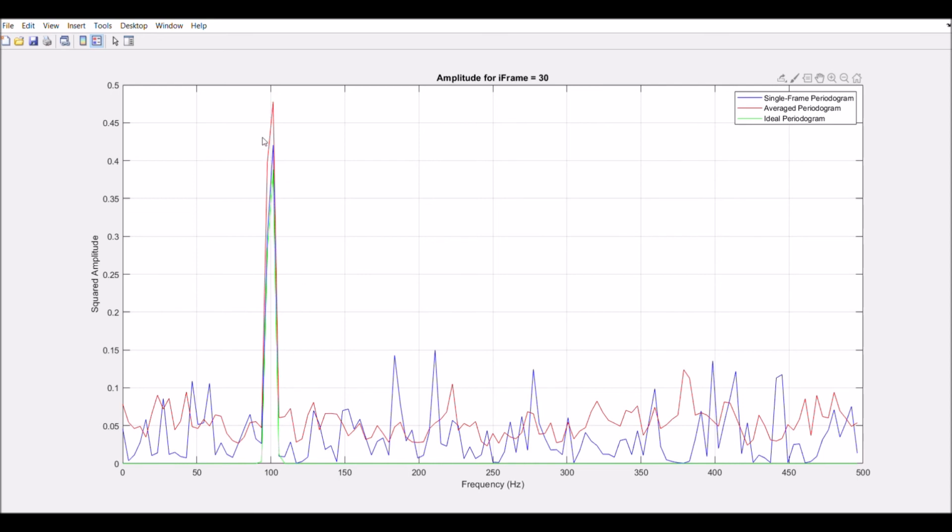And so we see that the peak is approximately where the other two peaks are, but two things have changed about the noise content. One, the bias, or the average value of the noise, has increased a little bit, but the variance of this noise has decreased, and so we don't see as many of these sharp spikes as we do in the blue data. Basically, what this non-coherent integration, or power spectrum averaging, does is increase the bias of the noise but decrease the noise variance, which makes it less likely for us to have large peaks that look like they could be signal content.